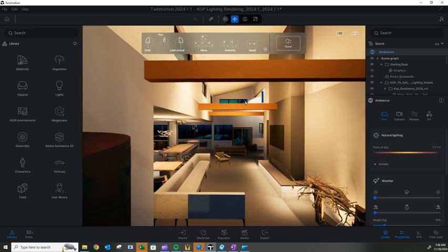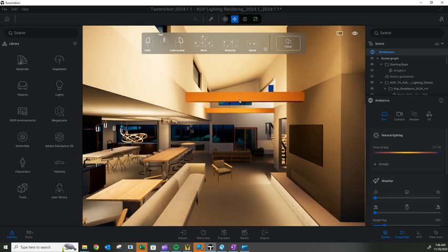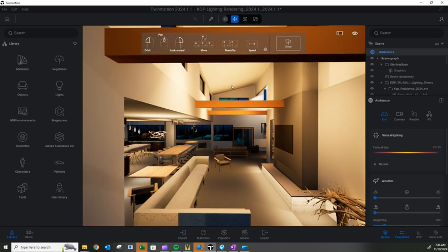You can see with these beams, I'll just go through the layers of light in this space. If I turn on, you'll see we have overhead downlights to push light with narrow optics as well, so you can push light all the way down from that high ceiling. If we do a wide flood, it's not even going to reach the ground, so we have narrow optics to get all the way down to the ground. We also have linear tape light up on top of the beams to cast up light into the ceiling. And what we're trying to do is just wash the space with light, wash the walls.